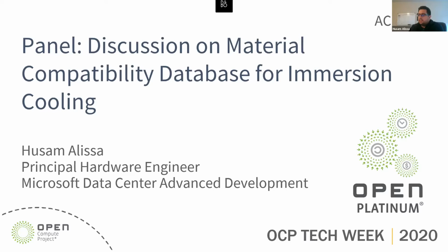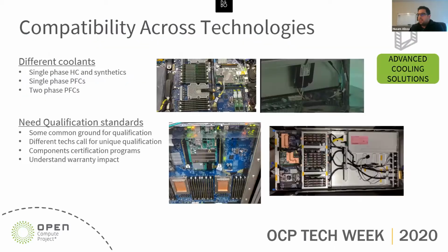Similarly, the compatibility discussion can be expanded to direct-to-chip liquid cooling. For example, in the discussion of direct chip cooling with cold plates, there is the list of wetted materials, the use of copper versus aluminum, concerns about galvanic corrosion, and selection of compatible coolant and material, whether it's water or PG.